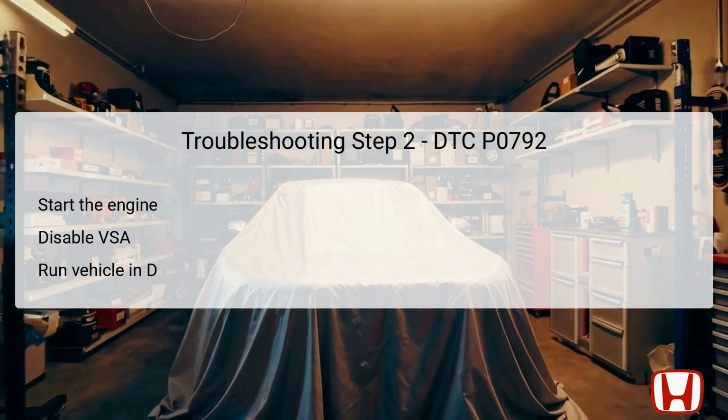After reaching the specified conditions, slow down and stop the vehicle to prepare for the next check. This step is vital for allowing the vehicle systems to recalibrate and ensuring that any intermittent faults may surface while monitoring sensor responses during the drive. Following the on-road testing, the third troubleshooting step requires checking for pending or confirmed DTCs using the HDS.